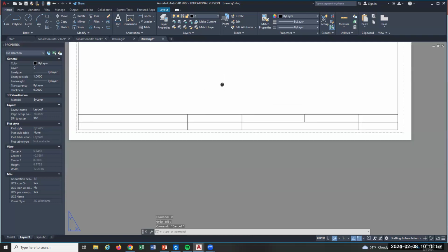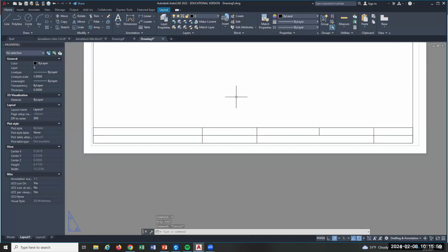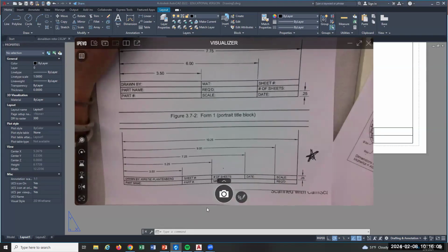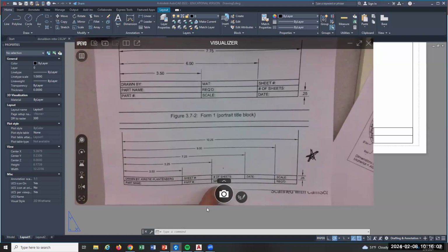Good? Yeah. All right, text. Let's talk about that a little bit because you've got text in this thing, right? In paper space, we don't have to deal with scaling of text. We can just put it in the size we want because we're literally writing on the paper, right? It's not ever going to be zoomed or anything. The paper is the paper size. So I think I put in the instructions that the text is 1/8 inch. Okay.